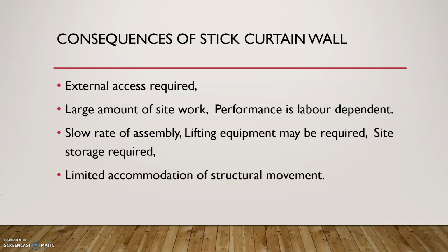If not, then later on you can see some sort of leakage on the facade or draft coming through the facade. Slow rate of assembly, lifting equipment may be required, and obviously site storage is required. Limited accommodation of structural movement.